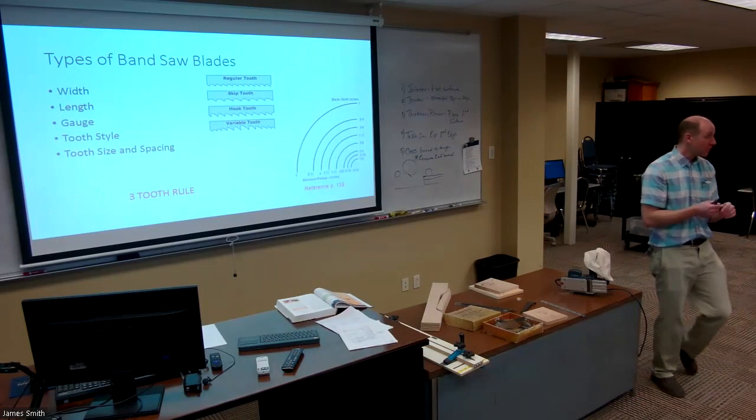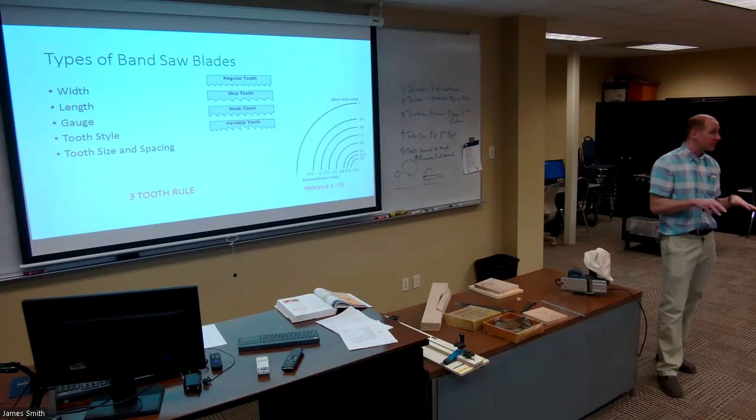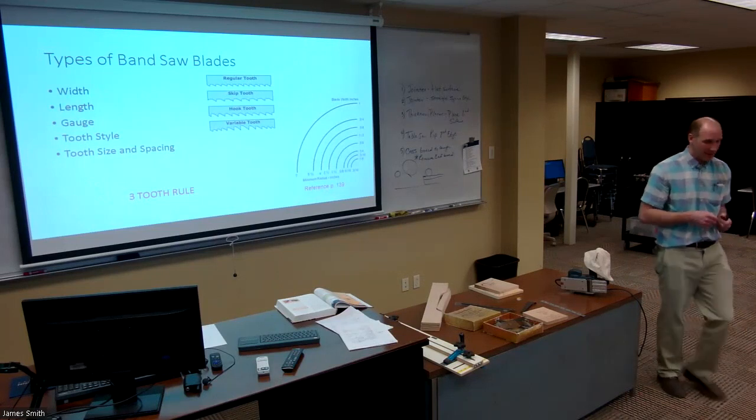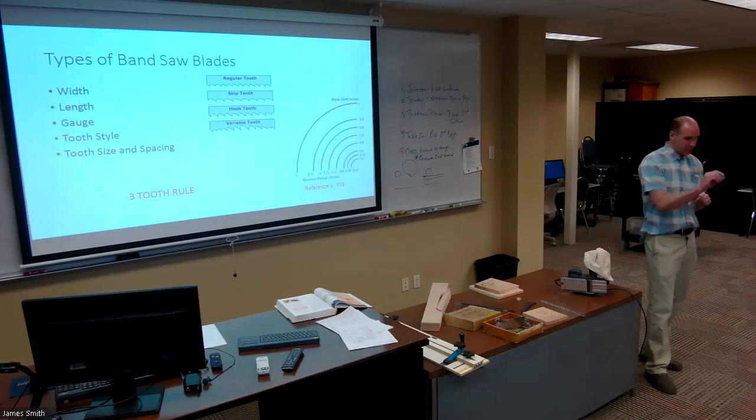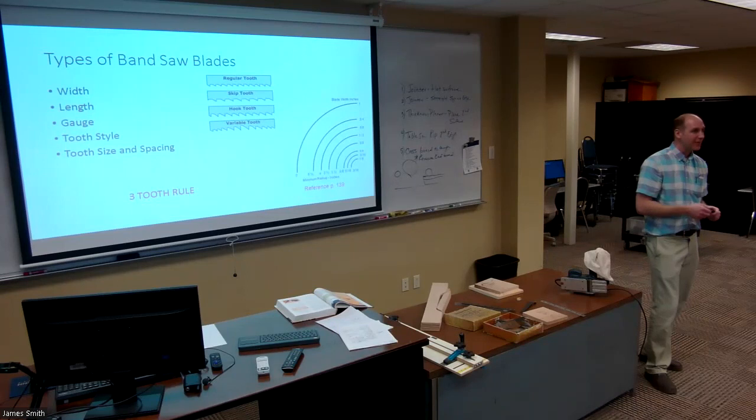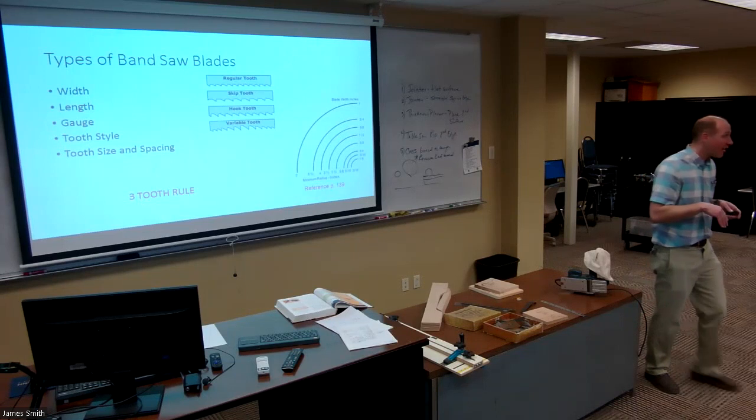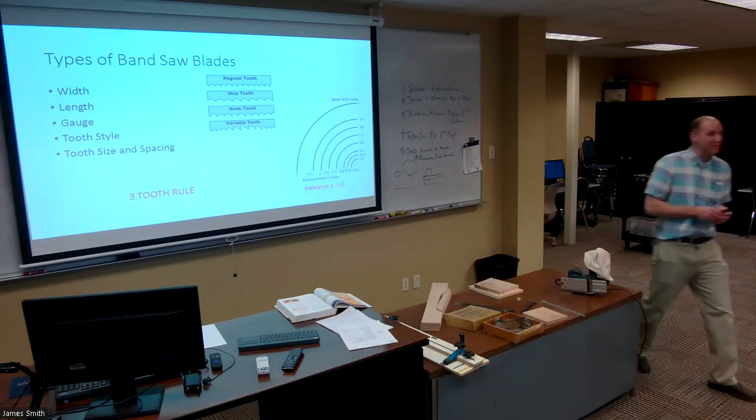Otherwise, you'll strip your teeth off, especially if you're cutting stainless steel. I had this happen last semester. I had a guy come in with a stainless steel sheet. It's so stiff we couldn't cut it on our metal brake, so we were going to make it work on a bandsaw. Very careful to feed it ever so slowly, and you could hear every time. We really didn't have any options, so I just decided to sacrifice the blade.